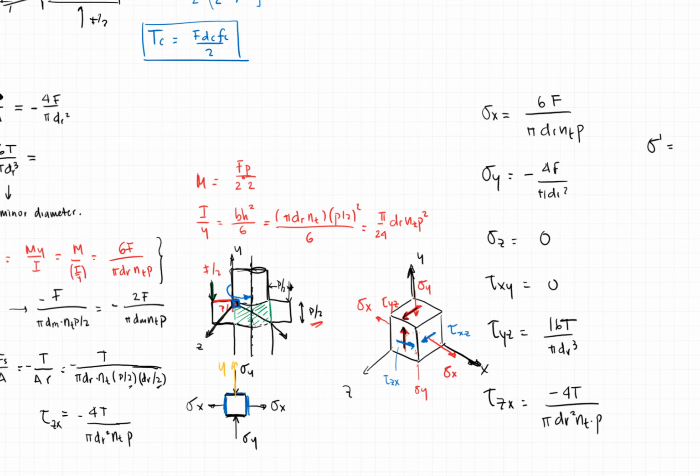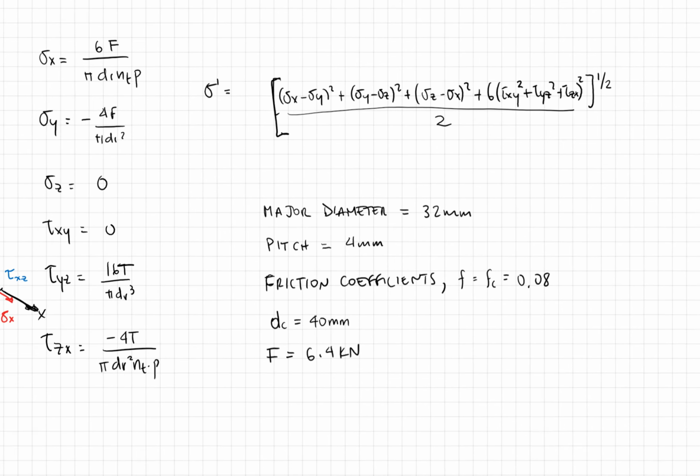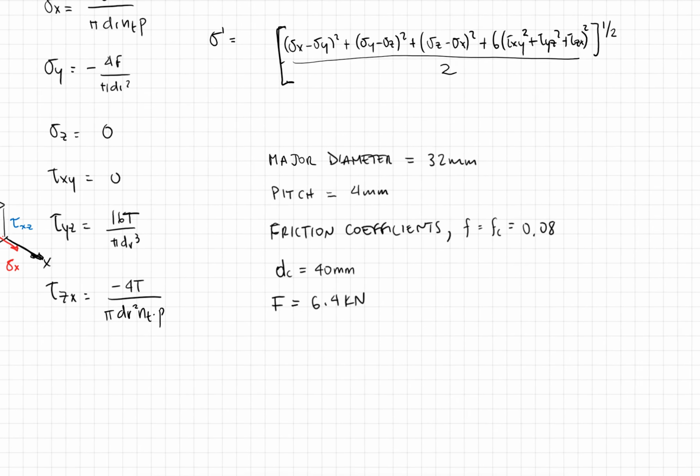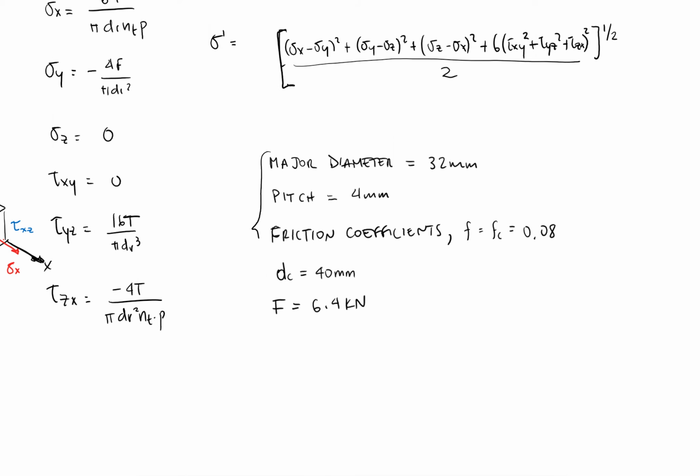This is example 8.1 from your book, the numbers that I'm giving you, so you can see how they solve this. But basically, if you know this data, you would be able to calculate things like the thread depth, all of the dimensional parameters: thread depth, thread width, the pitch diameter, the minor diameter. You're given the outer diameter, that's what you would measure.